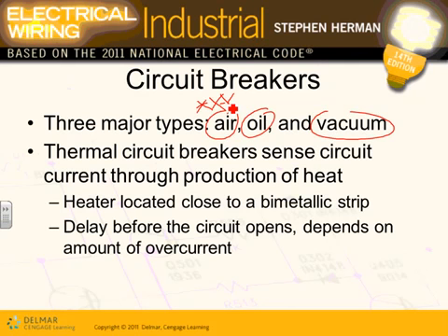What is a vacuum circuit breaker? They have a tube, guys, a little tube and contacts inside it, and they remove the air from it, so it's vacuum now. So when you open these contacts, you don't arc that much. The whole idea, guys, the reason why we have these three types, is to get rid of the arc. Every time you open a circuit, you create a huge arc that over time will damage the equipment. So the bigger the equipment, the more you need means of extinguishing the arc. So think of these as air, oil, or vacuum. So typically, guys, 99% of the time, you're going to be dealing in your career with air circuit breakers. Okay, so that's how they build them.